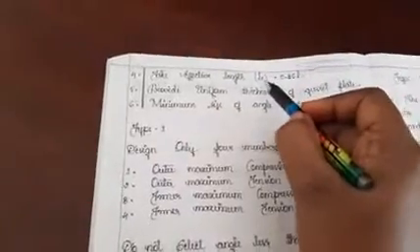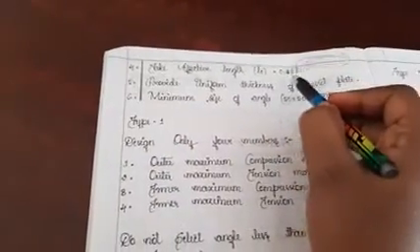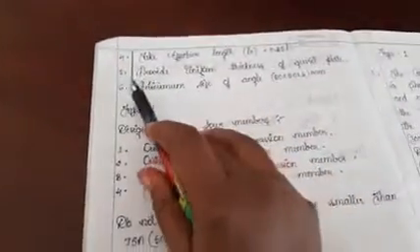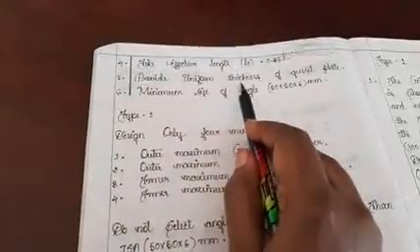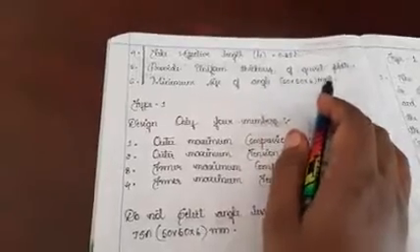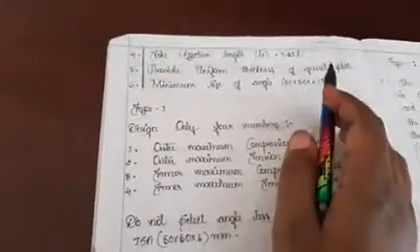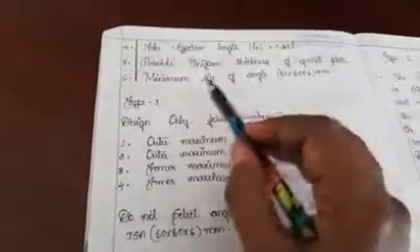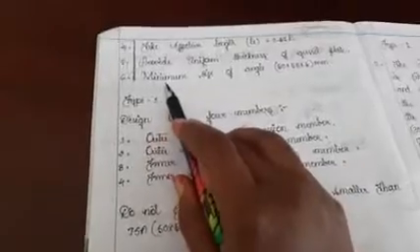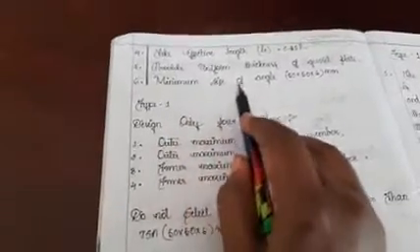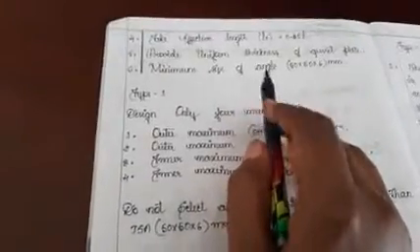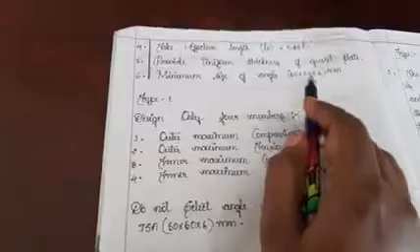Coming to the fourth point, take the effective length, that is L suffix E, equals 0.85 times L. Next, the fifth point is provide uniform thickness of gusset plate, in the sense 8 mm, 10 mm, 12 mm, 14 mm, 16 mm. In that way you need to provide a thickness for the gusset plate. The last point, the sixth point, is minimum size of angle. As I said earlier, while selecting an angle, the minimum size should be 50 by 50 by 6